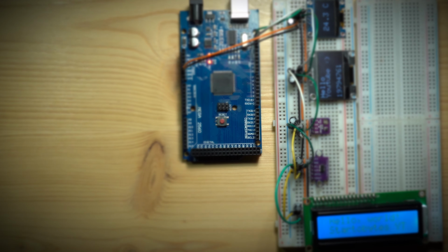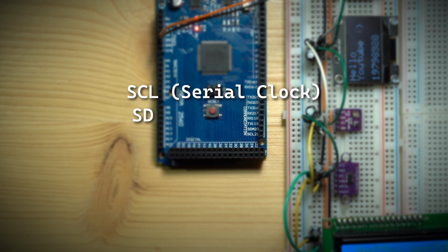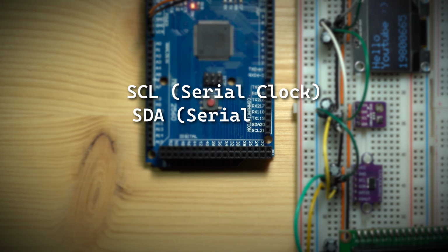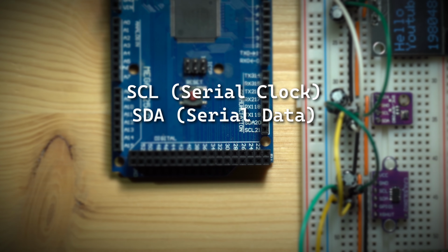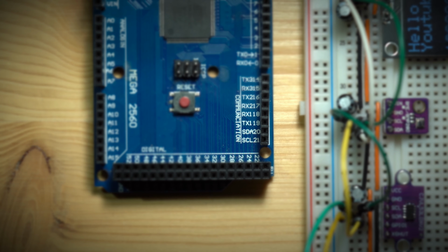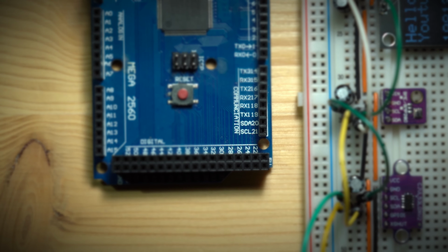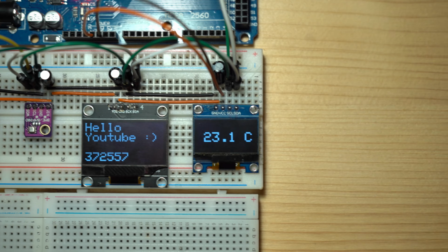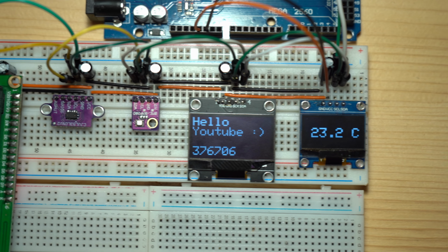Those 2 wires are SCL, which is the serial clock line, and SDA, which is the serial data wire that is used bidirectionally, meaning it's used to transmit and receive data. The serial clock line is used to carry the clock signal from the host device to all connected peripheral devices. The data wire carries the data from and to all connected devices on the bus.